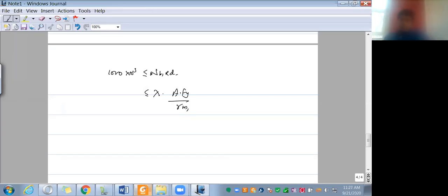So your chi value should be greater than or equal to 0.964. If the chi value is less than 0.964, it means your buckling resistance is lower than your squashing resistance. So your chi value should be greater than 0.964. If this clause is not satisfied, we need to choose a different section. Okay, so now let's see whether this can satisfy this requirement.